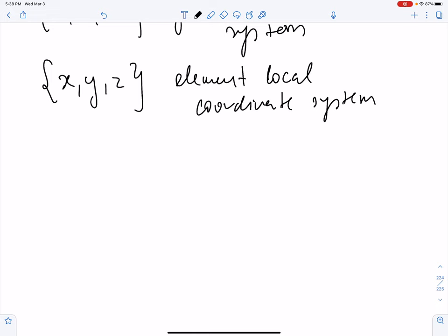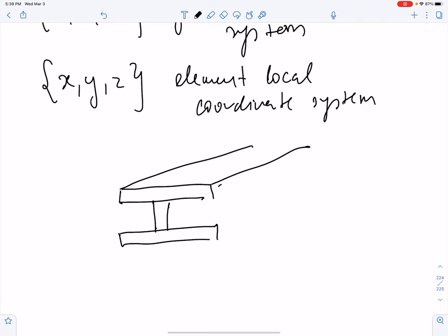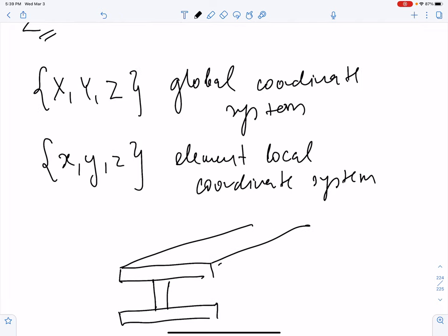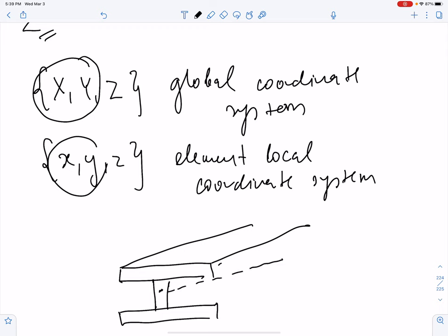And so basically, if you think of a structural member, for example, some kind of I-beam, often used in, say, steel construction, this keeps going. When we talk about the XY plane here, or little XY plane, this is really a plane of symmetry. So the little x-axis will go this way, the y-axis goes up. So this defines a plane of symmetry, and that's the plane that we're talking about, that passes through the plane of symmetry of the structural member here.